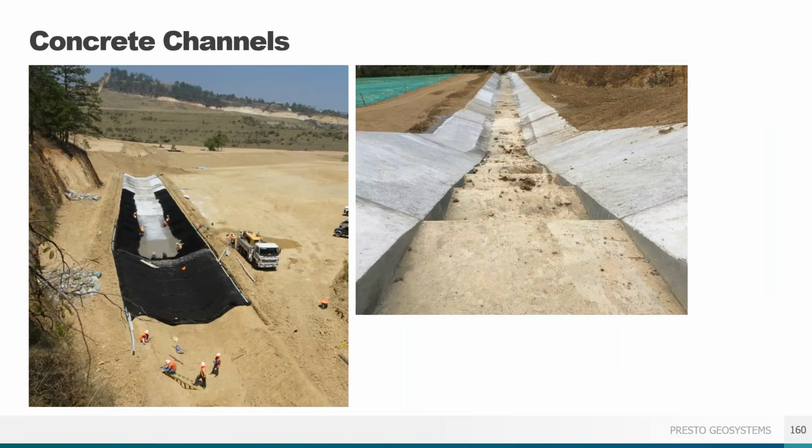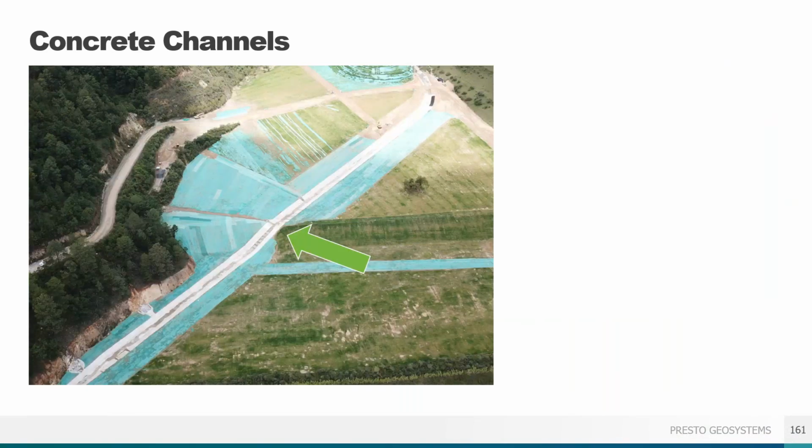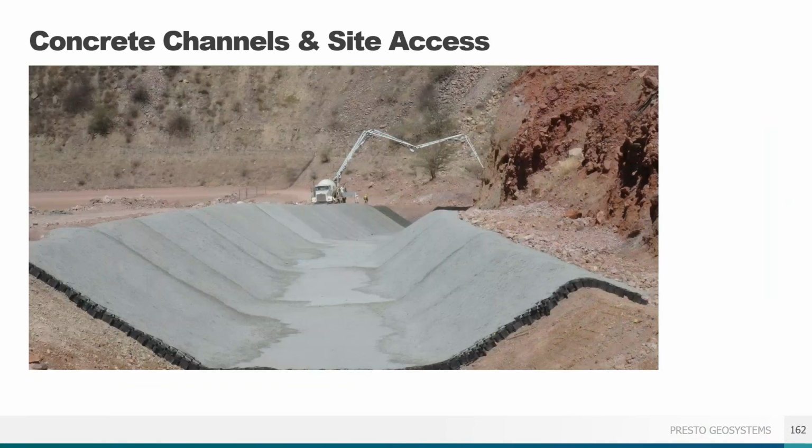This channel had a drop structure, rapids incorporated. Here you see the joining of that rapids to the rest of the GEOWEB channel with a drone view of the rapid structure here. A pro tip for concrete channel infill is to use a concrete boom pump, as seen here, or a line pump if you have an install easily accessed horizontally.